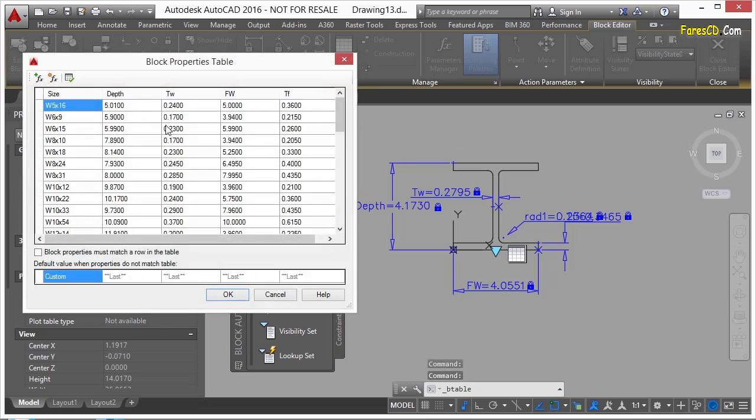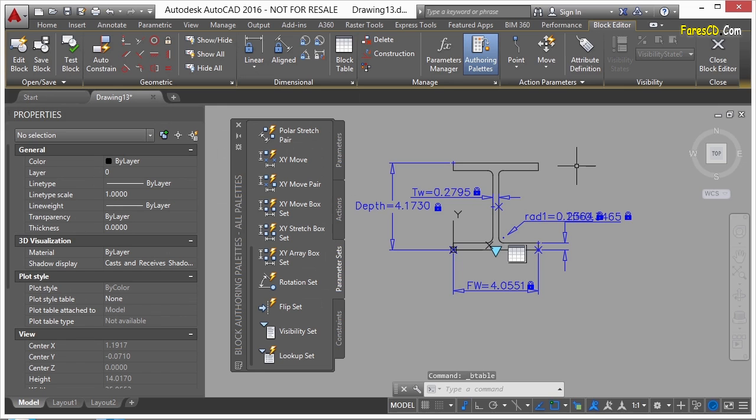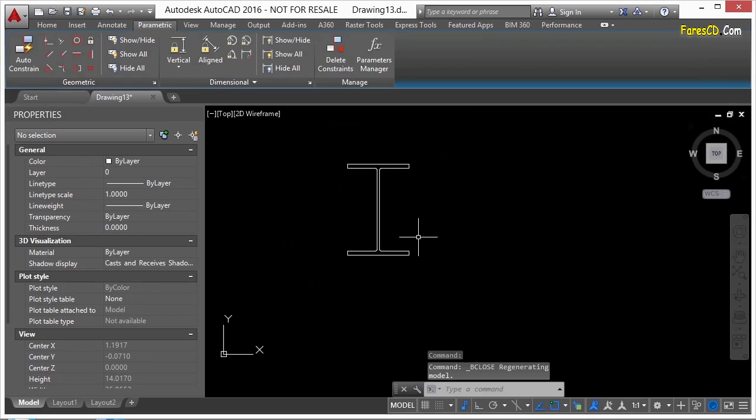But with these different constraints that I have, the dimensional constraints and the geometric constraints, I can create a block table that will change each of these different dimensions to whatever value I preset. And I can have one set of line work, just one basic shape, and then I can control all of its dimensions through my block. And I can only do that in this way because of parametric constraints. So that is a great application of geometric and dimensional constraints while fully constraining my object.